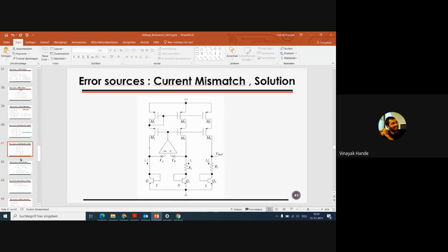No, actually here what we are making sure is that the top transistor is now our governing power, right? So the top transistor will try to make them exactly matched with each other, so that there will be no current mismatch. But again, this is not a fair solution as you pointed out. It will give better PSRR response, but systematic mismatch it will not help to the extent.